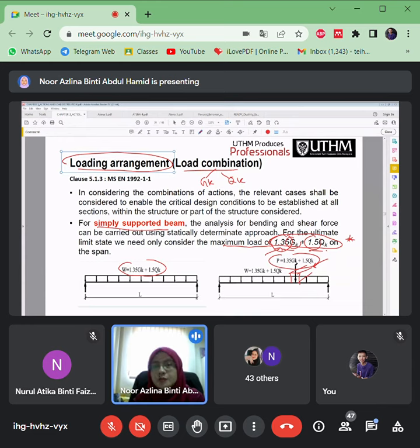It might be from the columns, or from the truss reactions, the truss systems reactions, right, that are applied to the beams as point loads here. So from this simply supported beam, it is quite simple. You need to come up with bending moment diagrams in order to know the maximum moment here.